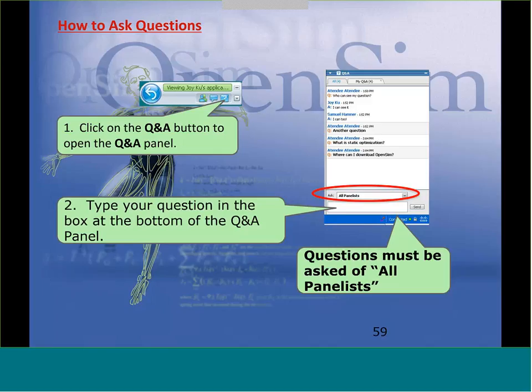Yeah, the patellofemoral ligament and the quadriceps mechanism were modeled with membrane elements, and they were embedded with springs, and the development of that structure had been validated in previous cadaveric work that we've used. But we used membrane elements because they carry load in the axial direction only, and they don't carry any load in bending.